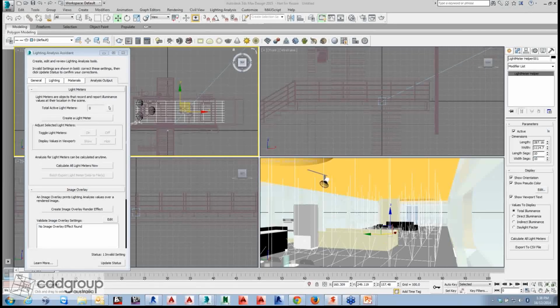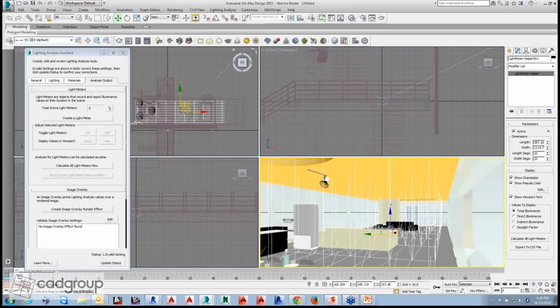It is also recommended to raise the light meter 30 inches from the floor or from the ground level, depending on where I'm using it. So I'm going to change this to 187 for now, so it's elevated 30 inches from the floor area.